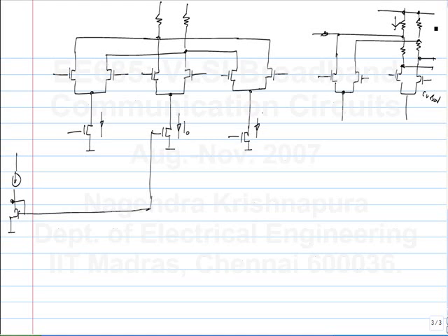Okay. But yeah, potentially you could vary these. You can realize these with MOS and vary them in a complementary fashion so that the total is the same or something. Okay. That's possible, but difficult, because you have to keep the MOS transistor in triode region for it to behave linearly. What else? How else can we vary the cursor weight, the coefficient weight?